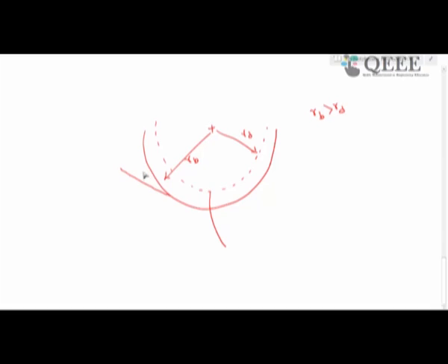That means whatever involute you generate has to finish at the base circle level; it cannot extend beyond it. So if at all there is a tooth profile in this portion, it is not involute, and we take it to be just a radially extended version of whatever happens here.